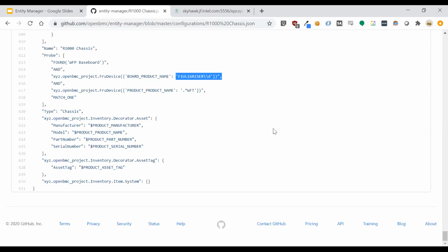There's a removes syntax where you can delete when. So you say you have the example I have for this is we have one system and it's in an open chassis, so it has certain fan clamps, and then when it's a closed chassis, we want to have stricter fan clamps because that platform is a closed chassis, so the heat restrictions are worse, so we need tighter clamps.